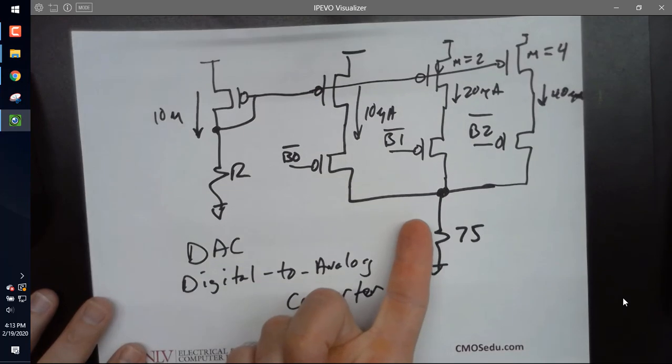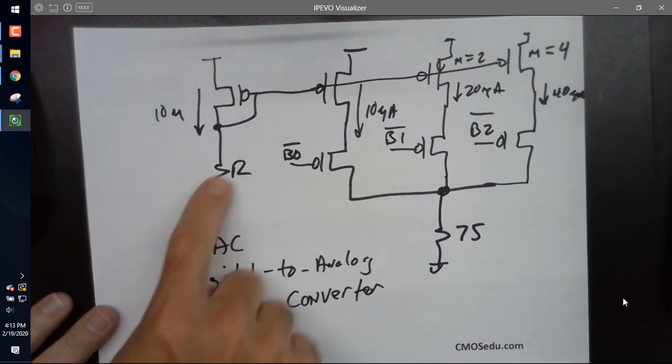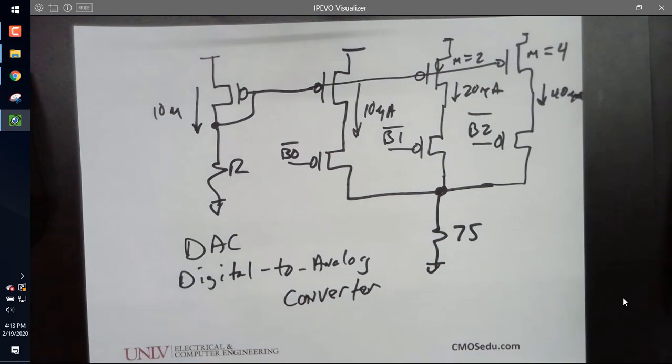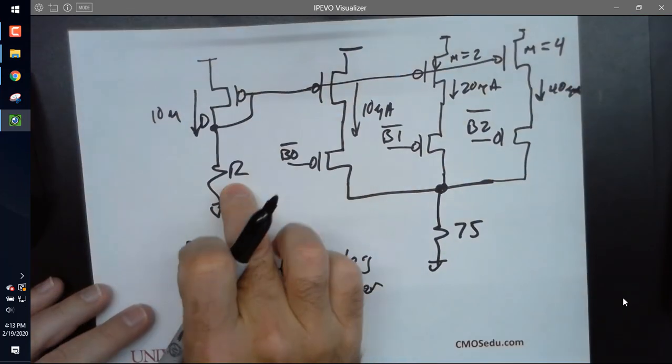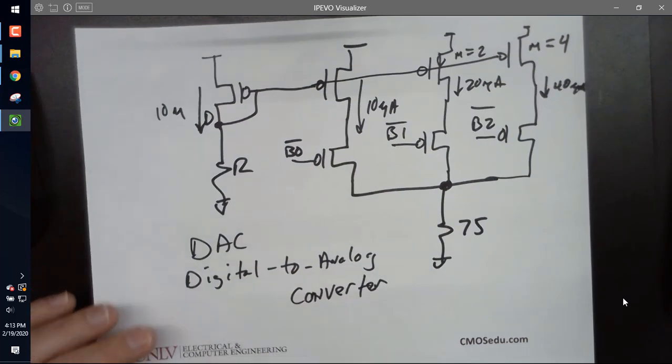So the power supply is dropping, and my monitor is getting dimmer. I don't want that. I want my monitor to stay at the same brightness. So I've got to come up with a way where instead of having the resistor here on the drain side of the circuit, I have the resistor some other place, or some other way to bias this. Does everybody see the problem?